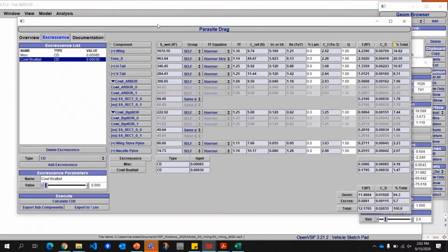However, the one really great thing about the one built into VSP Aero is when you're doing something like rotating blades on a propeller or a rotor, it's able to calculate that local velocity, local Mach number and local drag as the velocity varies out the radius of a blade, and calculate that drag so that it actually increments the power required of the rotor, based on that parasite term, not just the induced term. And that's of course something that you wouldn't even be able to get out of a normal airplane analysis for that parasite term.